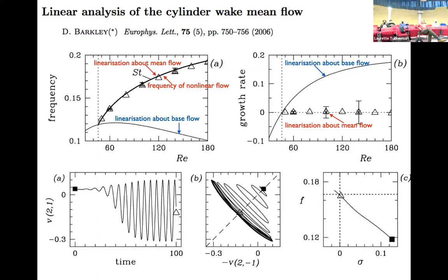Now, this is an interesting thing. This is a phase portrait where you have a V at 2 different places, and the base flow is here. This is the unstable, steady cylinder wake here in black. And look what it does. If it were the Hopf bifurcation that's illustrated in your nonlinear dynamics textbooks, it would oscillate around this black thing.